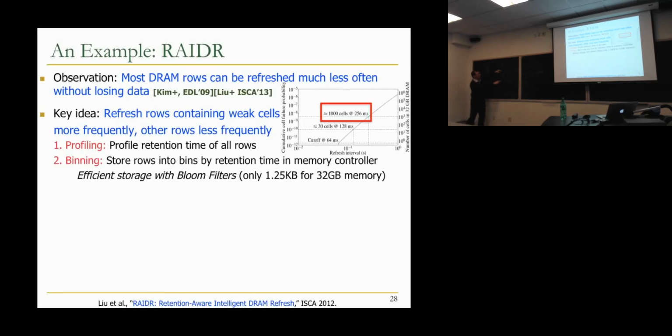You basically store 1,000 bits for 1,000,000 rows and indicate the membership of an address going through a hash function, right? And setting a bit that corresponds to that hash function and the address. So that's the idea of a Bloom filter. You can represent set membership with a much more compact data structure. It could be software, it could be hardware, right? This is much more implementable in hardware, right?